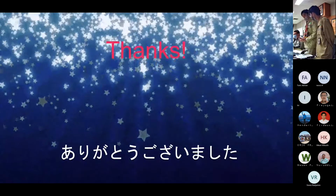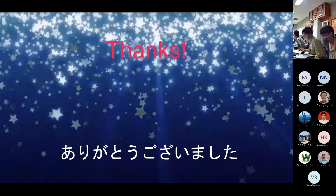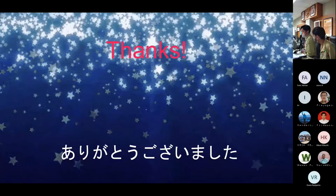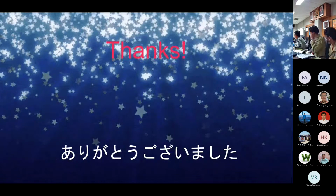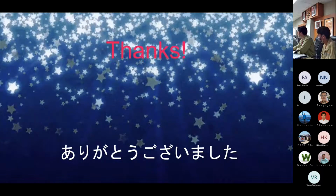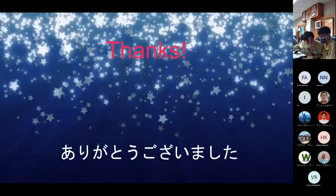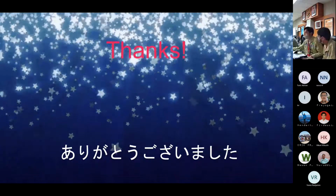As for the source of the idea, we consulted because after the annual shutdown 2020, the WTP has a higher flow, so the higher consumption of limestone and calcium hydroxide. So it means the scaling growth is quite faster compared to previously. Previously we had 10 to 12 months before cleaning, now reduced to 6 to 8 months.